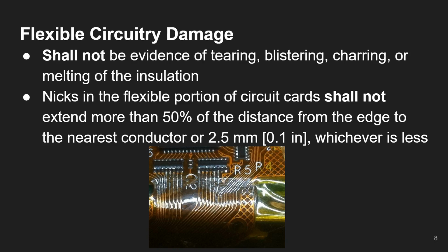Here, the nicks or haloing along the rigid part of the edge of the rigid flex, which is this flexible printed circuitry, cutouts and unsupported holes shall not exceed more than 50% of the distance from the edge to the nearest conductor, or we can say 2.5 mm, whichever is less.